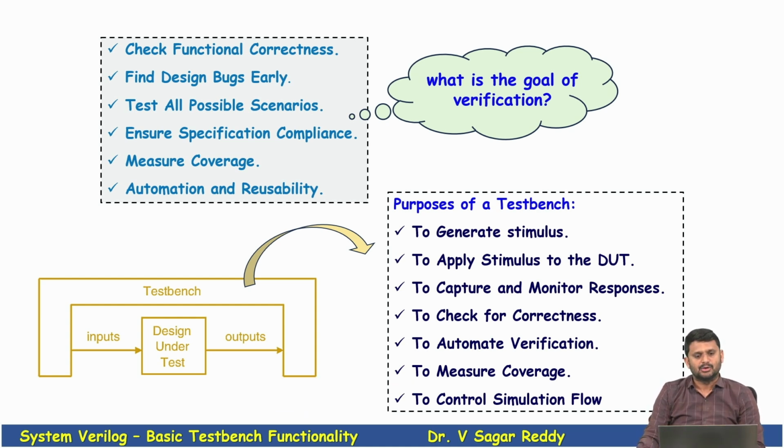The second one is to capture and monitor responses: observe the DUT's outputs in response to the applied inputs. Then to check for correctness: compare DUT outputs with expected golden results using checkers or scoreboards, and detect functional errors automatically. To automate verification: reduce manual checking by automating the test process, which enables regression testing, running multiple tests automatically. And to measure coverage: ensure all the features and corner cases of the design are tested, which helps verify completeness of testing.